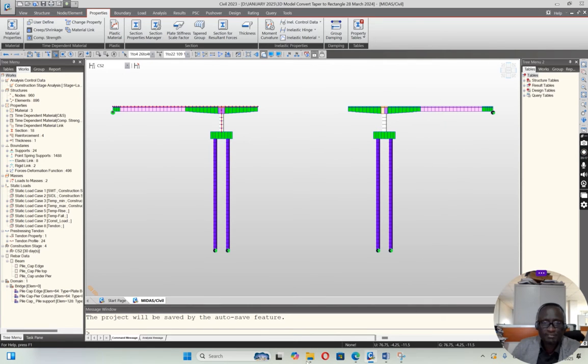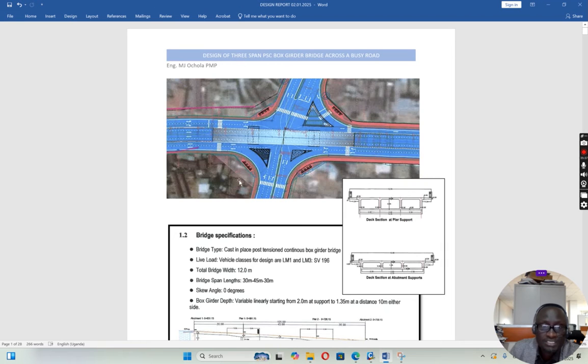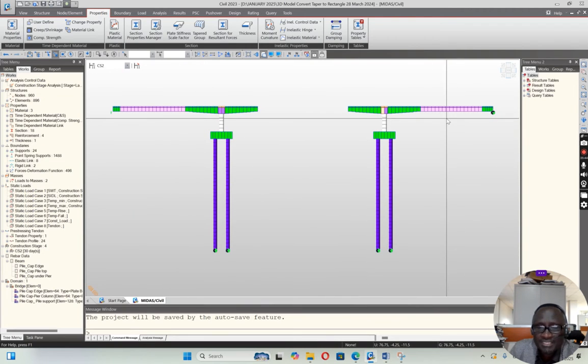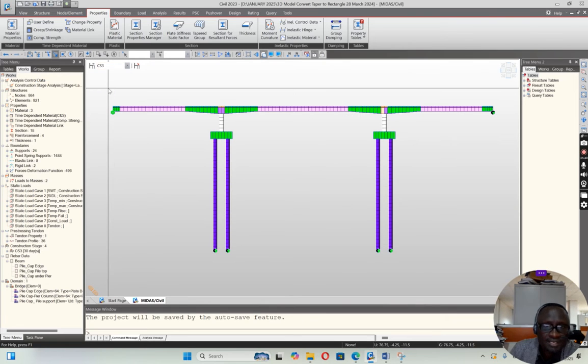It would have been 3 if we first did up to the pile, then this pier, but I've done it up to that, so 3 is to have these 2 supports. Then the third one is where you now open this area. After the concrete has gained strength, you open this area with steel constraint. Then you allow diversion here, which is demonstrated here. You allow traffic to move here, and you create this side and that side. Then you come and do your third stage.